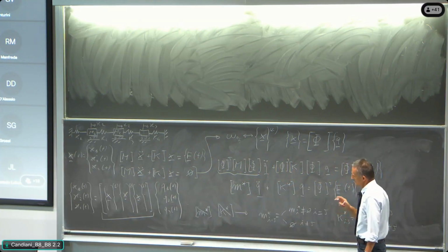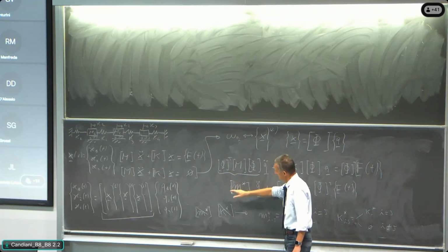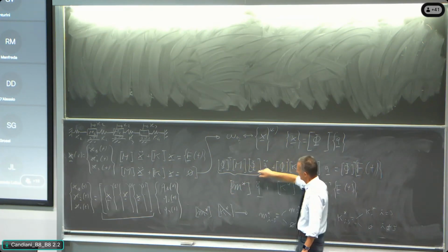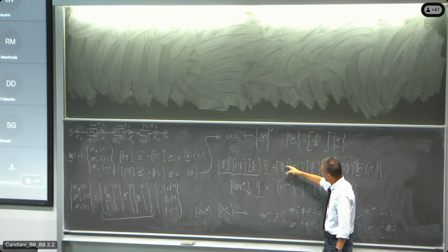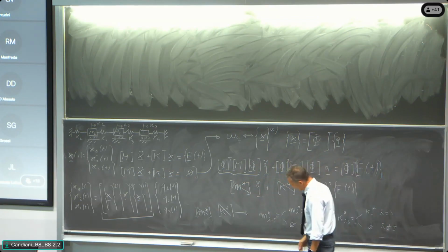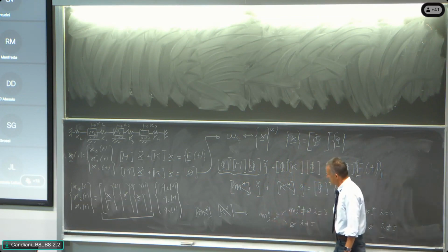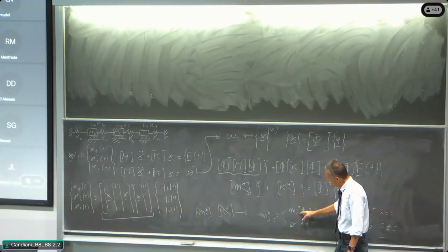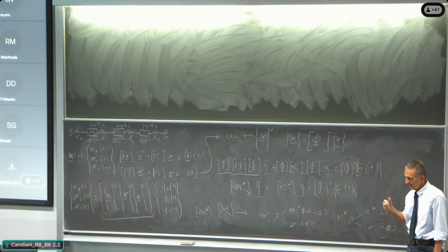Given those small constraints, the product phi transpose M phi makes a diagonal matrix, and phi transpose K phi makes a diagonal matrix. M star ij, when i is equal to j, we call Mi star, meaning the modal mass of the ith mode.